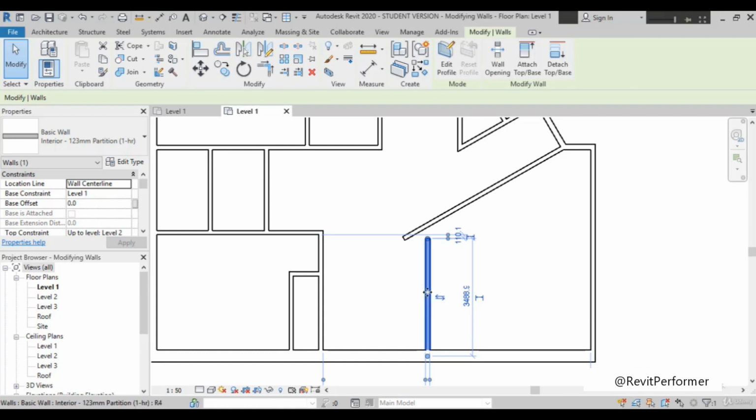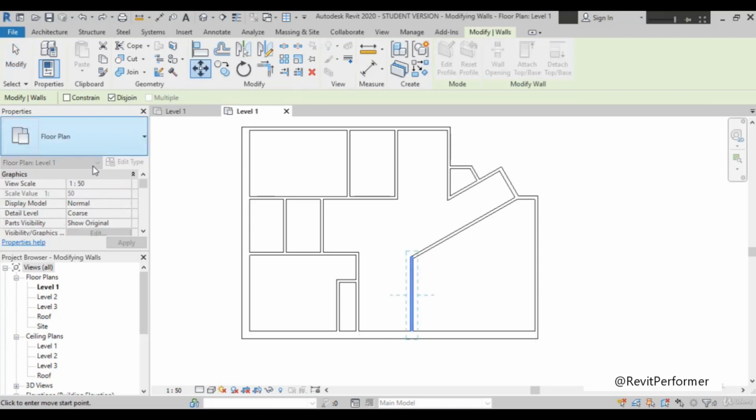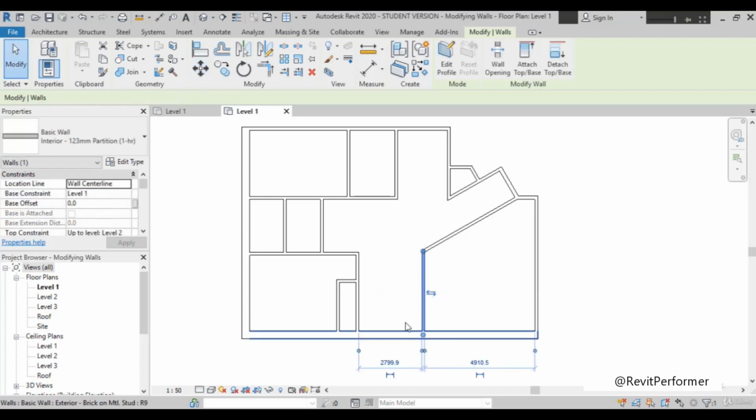That is because when you go back and select the move command, you see here the disjoint option is on. That is why it goes in a direction without joining this. If you uncheck the box here and then move it, you will find it in the right position. However, whenever you use this command, precision is not maintained in the moving command, so you have to use